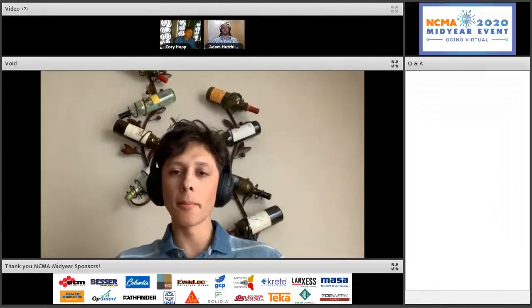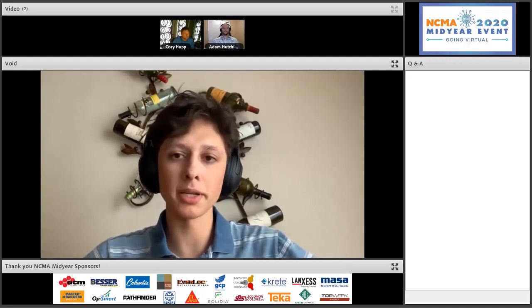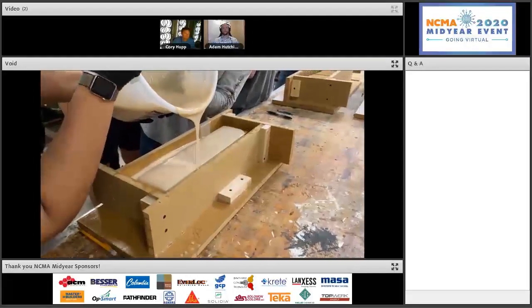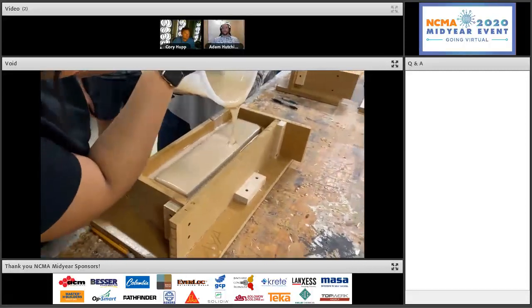So moving into the production side of the brick, we started first by laminating MDF sheets to form our block, which would then be used to CNC out our brick design using our Rhino 3D file. And then from there, we sanded the brick down, sealed it, sprayed a non-stick formula on it, and then bolted it to the bottom of our other MDF form that we'd created. And this would essentially be used to house the polyurethane that we'd be pouring in the empty space between the block and the form.